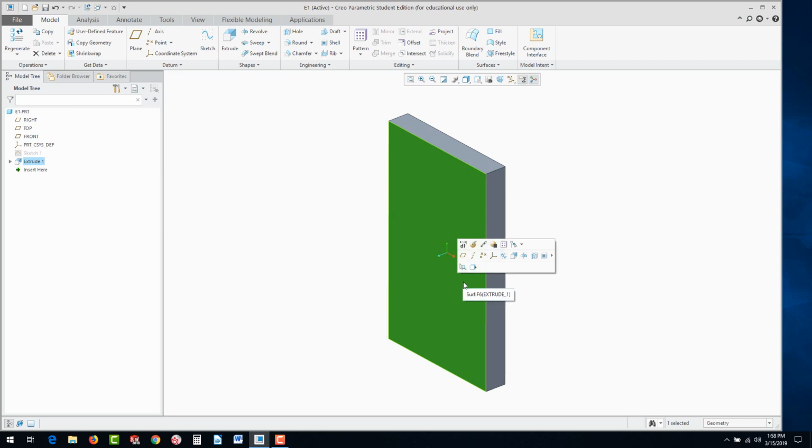So that being said, when you click on this, you get a number of options. You could edit the dimensions that were in the original model. You could edit the definition, that's the extrusion depth that we selected, or direction. There's also some other things I'm not going to get into just yet. There's some quick launch tools here, like if you want to extrude, if you want to make a plane, and